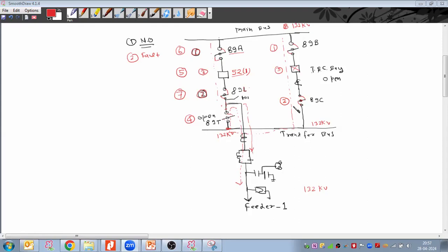Okay. What do you say? Breaker open, then isolator. That was my query. Now it's clear that while opening the isolator, it may not satisfy the condition of zero potential difference. Yes, zero potential is a concern only for closing, not for opening.